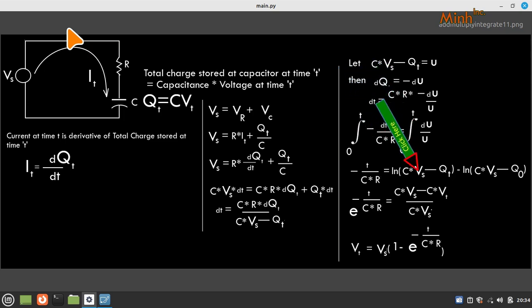then I get an equation like voltage across the capacitor at any moment is like this, at any time t, with CR. Okay, so this is the differential equation. We started with this and then R into I, where I at any moment is dq by dt, and Q(t) by C anyway we have. Now we are just shifting left and right. Now we have two variables, dt and dq. So left, right we do and we reach here.